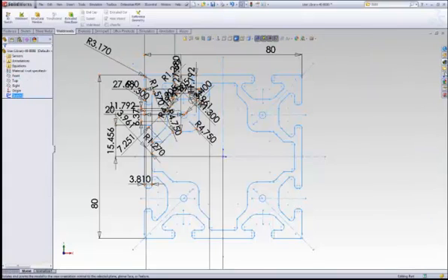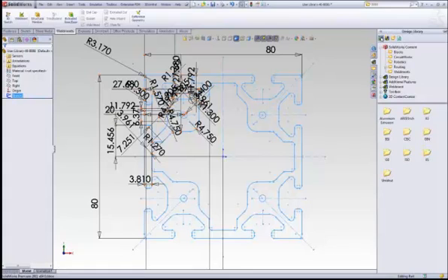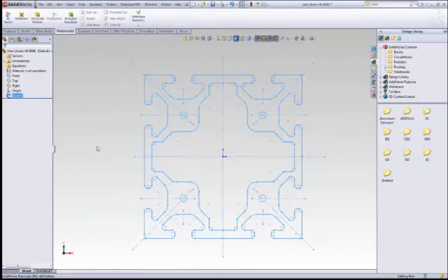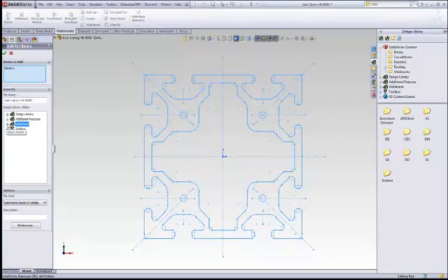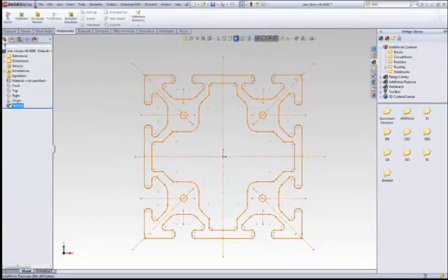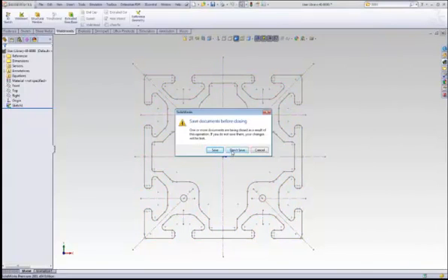Again, choose that sketch. Add to library. Pick that button over there. Okay. And choose where you want to place it. So here I have a folder that I already created for this. And there's a couple things you want to do. Make sure that your file name is put in. I'll just use the same thing for description. Make sure the file type is a library feature part. Don't leave it as a block. Okay, library feature part, and accept that. You'll notice that this little L shows up over that sketch. So now we'll go ahead and close this.